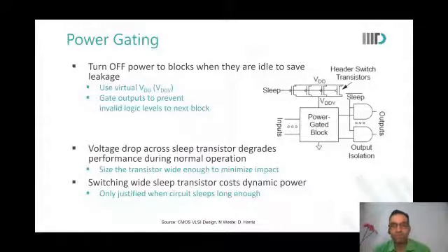So, what is this output? What output am I taking out from here? I mean, this would be the power gated block, not my PDN, the pull up or the pull down network. So let us say the power gated block only had the NAND gate. Okay, so it is the complete gate. The output of the NAND gate that we're talking about. So we are talking in terms of the complete gate, not the pull down or the pull up.